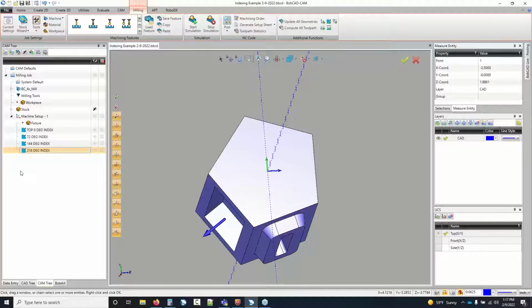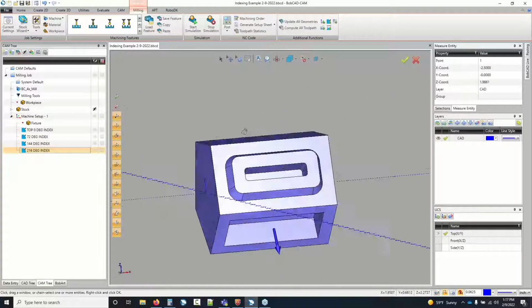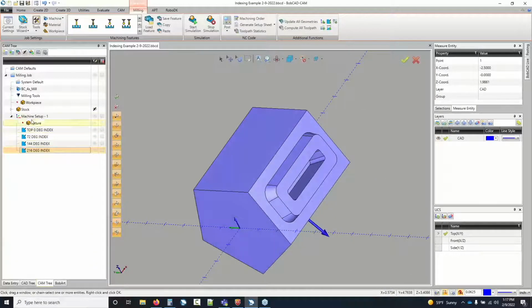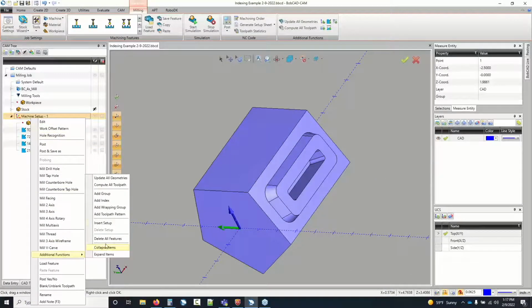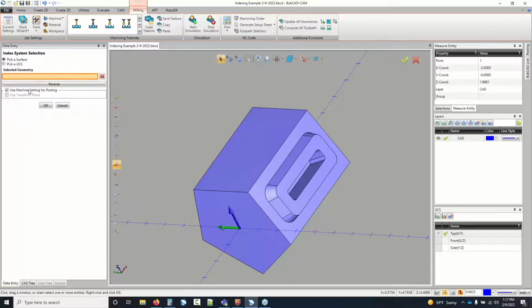And finally, the last one is going to be the one that's got this little 3D bit to it. So we do have to use a 3-axis toolpath on that. But I'm going to add my index. Now, there's two places I could pick. I could pick off this floor, or I could pick off this face. And I usually prefer to pick off the face, because then it knows that this is 0. So when we go to make our cuts for the depth we need to cut for the 3-axis and the depth of the inside, it's all based off this being 0. So this one will have a different depth when we face it off, but that shouldn't be a problem.